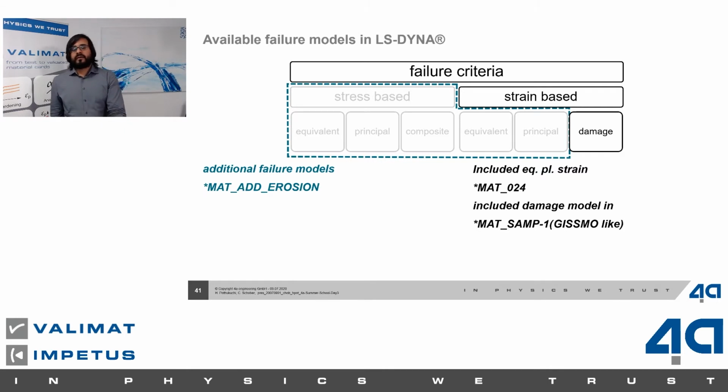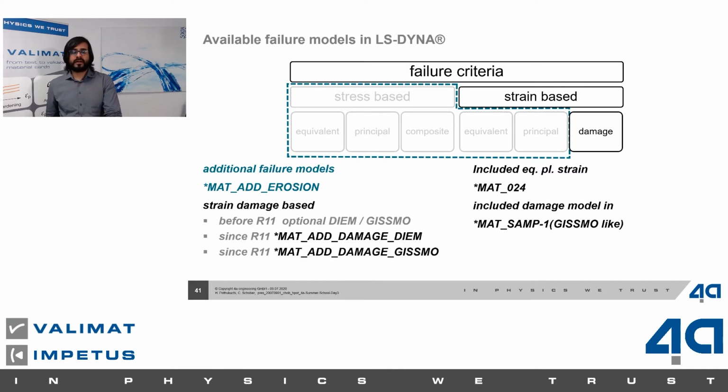Okay, then basically the additional failure models in LS-DYNA with the keyword MAT_ADD_EROSION. In these we have the options between DIEM and GISSMO. DIEM is your classical damage initiation and evolution model. GISSMO is a more specialized approach in failure.